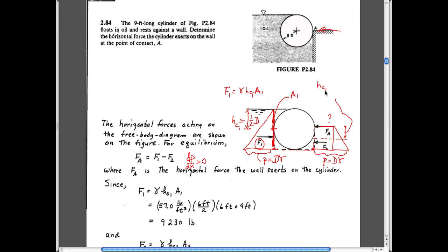So HC2 is going to be equal to, no, sorry, not that. It's this, right? HC2 is going to be d over 2, which is the distance to get to this point, plus d over 4. Complicated way of just saying it's the half height of this length here, right? But you can calculate what that is. And so that would give you the pressure at this point.